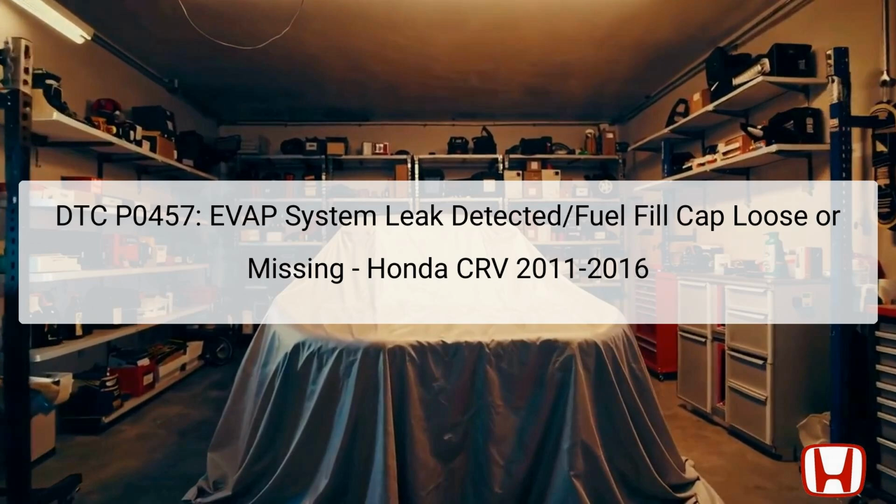The Diagnostic Trouble Code, DTC P0457, indicates that a leak has been detected within the evaporative emissions control system, specifically pointing towards a loose or missing fuel fill cap. The evaporative emissions control system reduces harmful emissions from evaporating fuel in your vehicle's fuel tank and prevents gasoline vapors from escaping into the atmosphere.